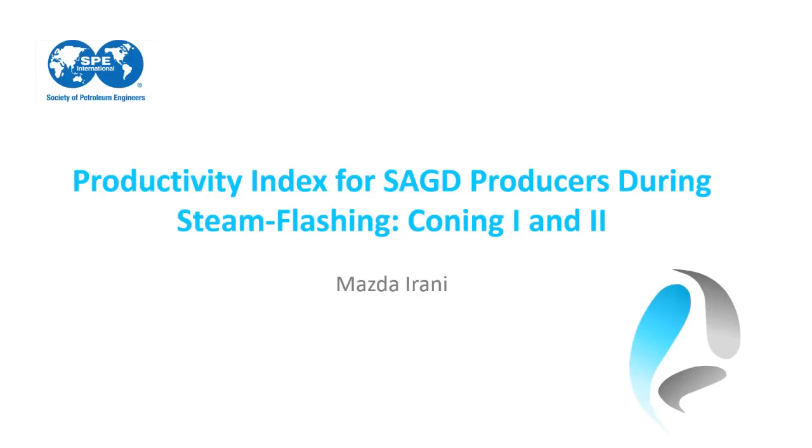In this presentation, I'm presenting the novel productivity index that's been used for SAGD producers, and now it's modified for steam flashing effects. We have two models, called Coning 1 and Coning 2, that have been implemented, and we're going to discuss the effects.